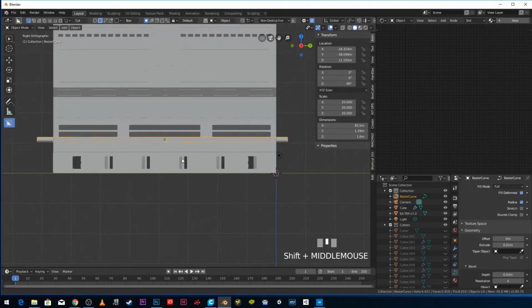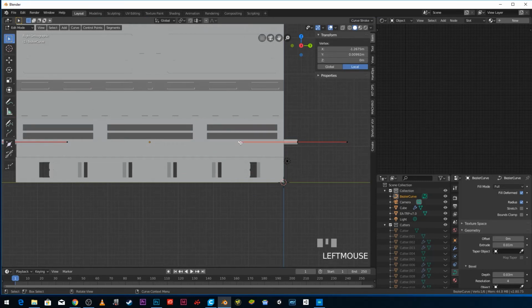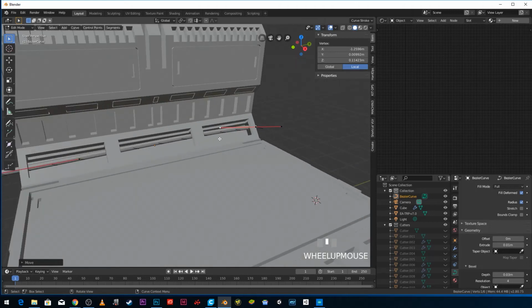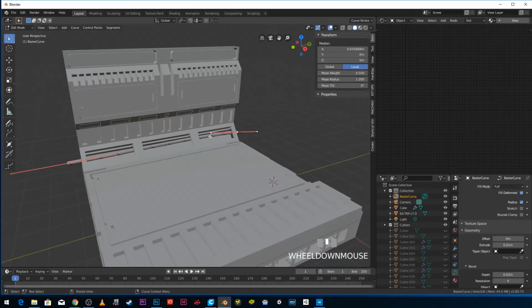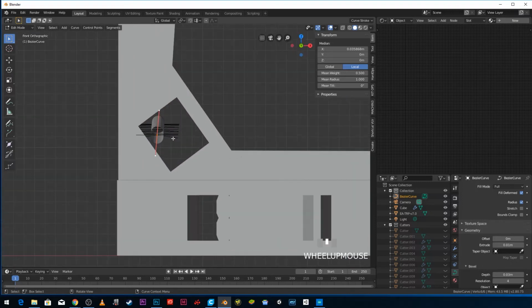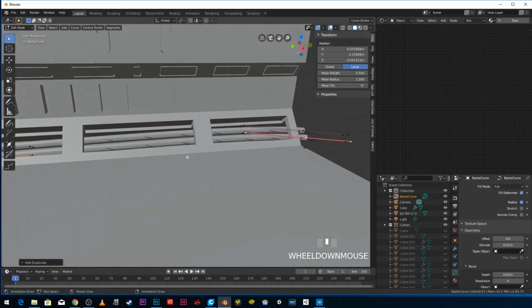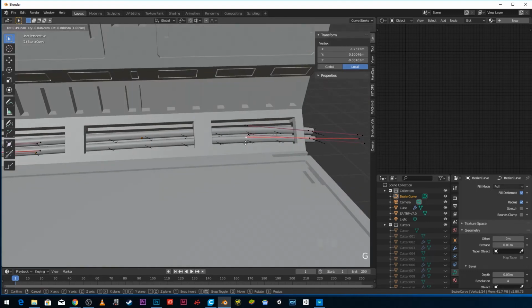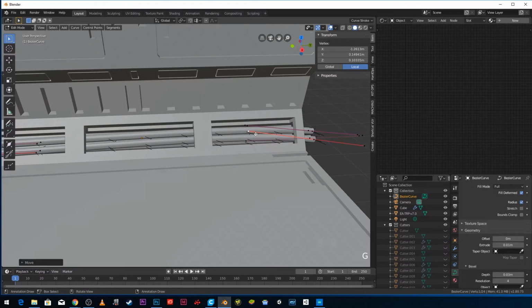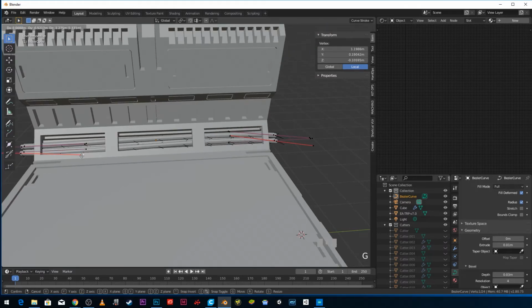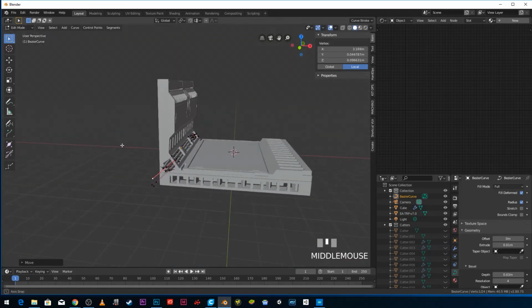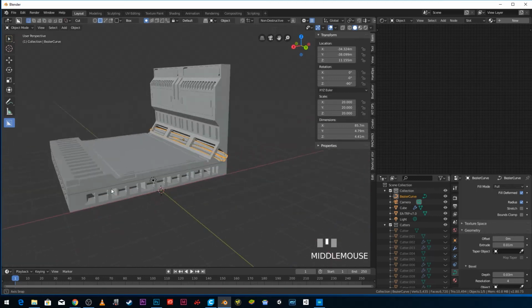Okay. So, and there's numerous ways to do this. If you make a cylinder and do it that way, you know, that's equally fine. But you can't do this down with the cylinder. You can't curve it, so that doesn't look completely symmetrical. So I pressed A to select all the vertices. All of the points. And I can go Shift D, Shift D, and Shift D, and then we'll go in here and see if we can just move these back a little bit to make it a bit more, to look a little more real. Okay, so they're my cables.